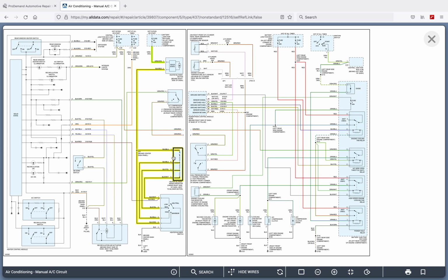If I click on this box, you can see that box is connected to multiple other circuits. So this feeds now our heater blower switch. This heater blower switch, I know this makes it look kind of confusing. This is one continuous path. Here's our power supply, here's our engineered load. If I was in low speed, I would divert through this path right here, go to ground.